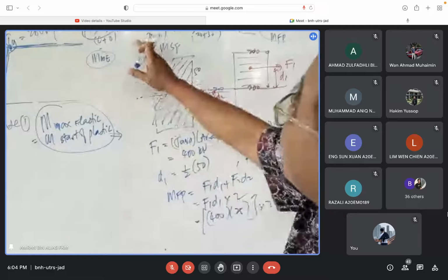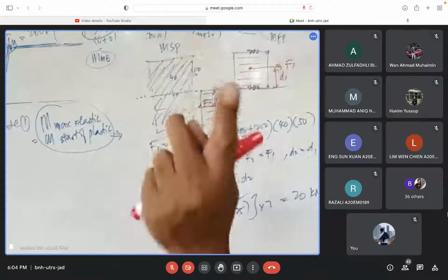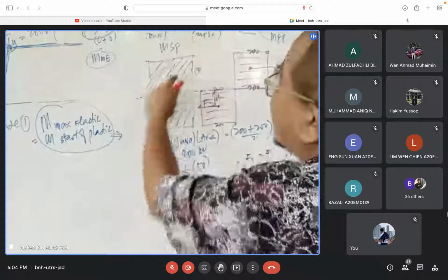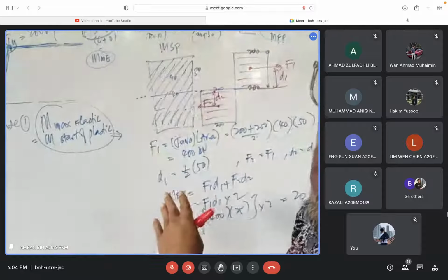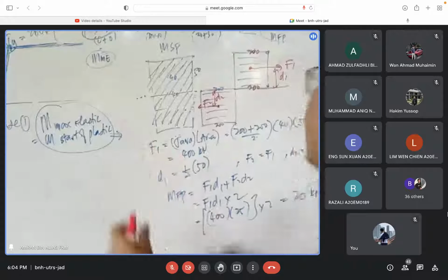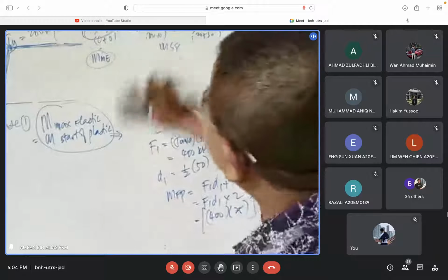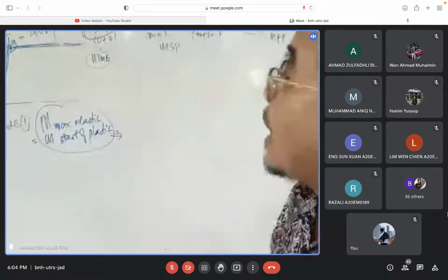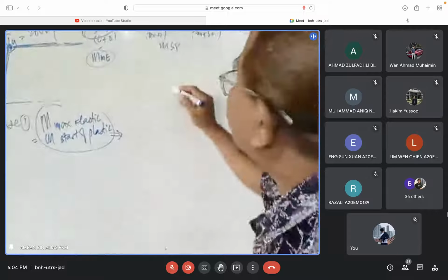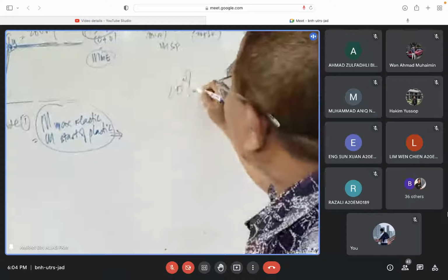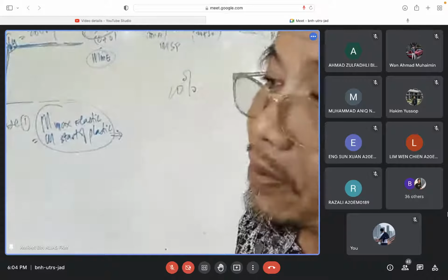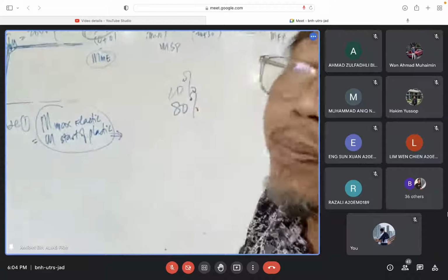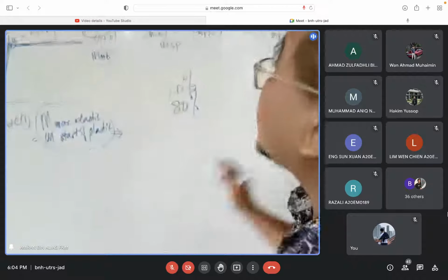That's how. See that? So then we decide. This is 30 and 30. 30 mm here and 30 mm. Easy for you to decide how much is plastic. Because say 10 mm on the top, 10 mm on the bottom. Sometimes it doesn't say like that. Sometimes it's 20% of the surface is plastic. That means 80% is still elastic, right? Yes. So how do we decide that?